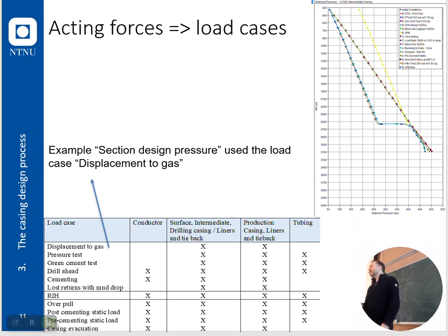Imagine that you pressure test after 2 hours when the cement is like that sand. It never goes back and fills the void. What's going to come down there? The liquid from the top comes down, and you have channeling, and there's no bond between your casing and the cement, or the cement and the formation. You ruined it. Green cement test means that you're pressure testing within the hour after placing the cement, and you're testing to the same level as the pressure test.